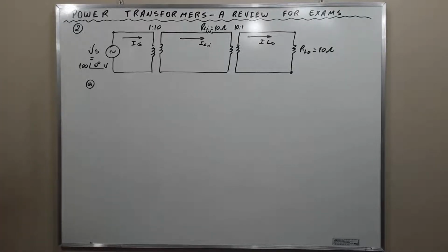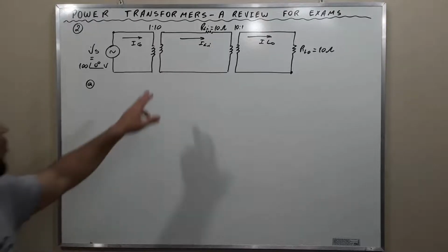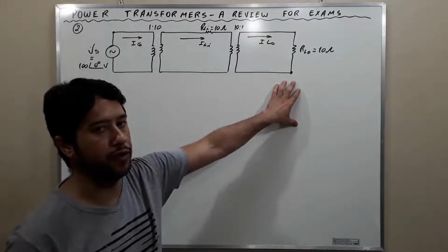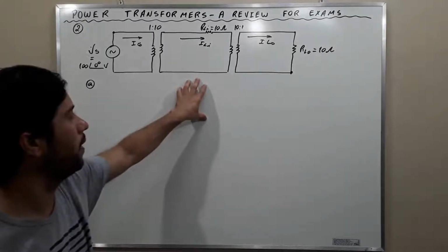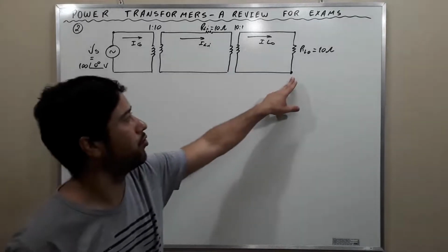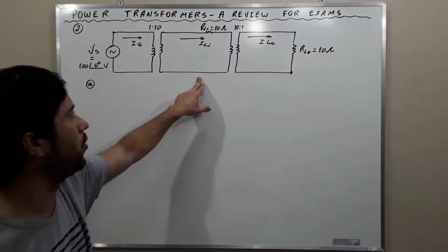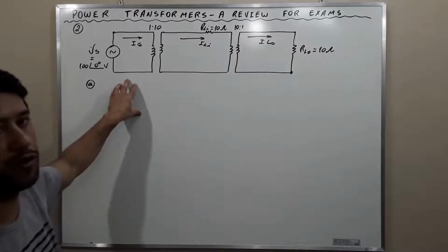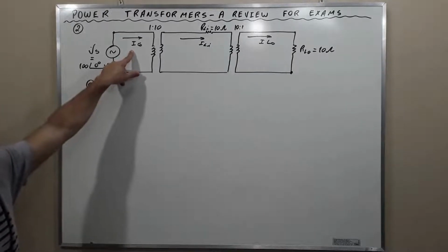Now we need to measure the importance of putting transformers in power systems, and assess whether we can greatly diminish power losses along cables when we use power transformers. Firstly, we refer the load impedance to the line region, combine it with the line impedance, and refer it to the region of the generator to calculate the current of the generator.